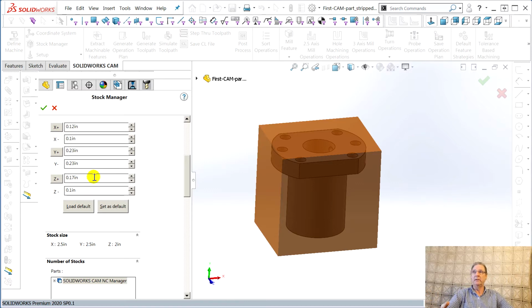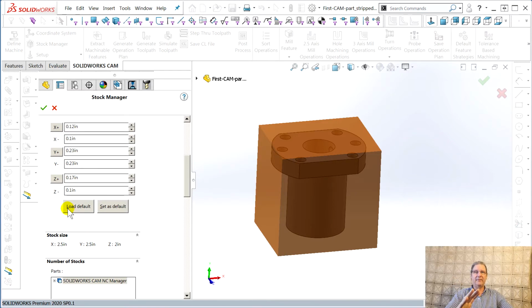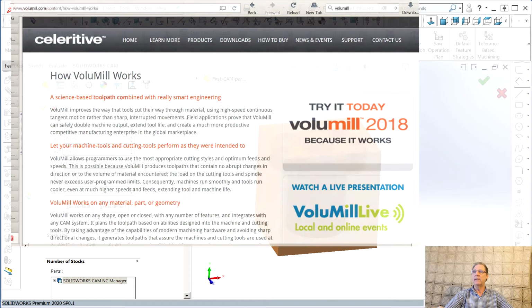Maybe this is improved in the $2,500 package, $3,000 with maintenance, SolidWorks CAM Professional, equal to CAMWorks Premium. It gets you Volume Mill, which is an adaptive machining thing that keeps constant tool loads, goes hogging through metal real fast, supposed to be cool guy stuff, similar to iMachining. Anyway, my machinist buddy said it's a third-party company that sells this adaptive machining to a lot of different CAM manufacturers. I don't know if that's true or not.